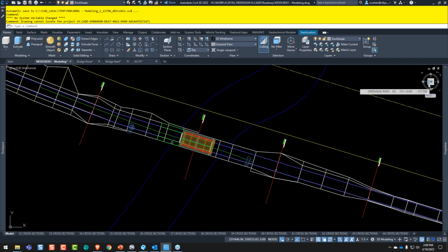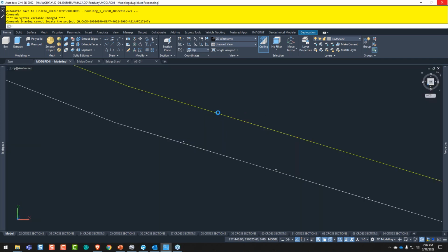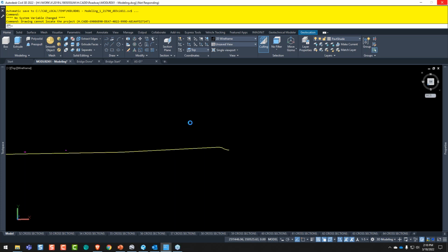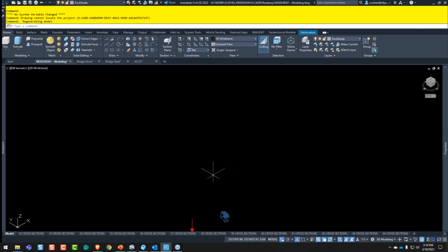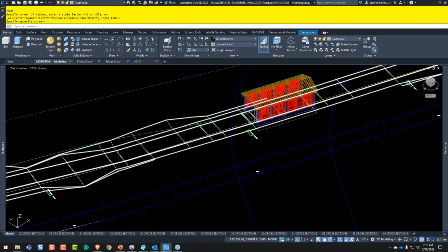And if we look at this in 3D real quickly, I'll do a southwest isometric view. Hopefully my computer will be okay with that. Should be just fine. But basically, I put that in here, but as you're drafting or creating it, it's actually better to just do it at 0, 0. You don't need to put it in the coordinate system. In fact, I found some issues when doing that, because it was changing my view a little bit differently when I would rotate the view in 3D. Ignore those glyphs, that's just the camera. But you can see here, I did actually put it on the path, right?